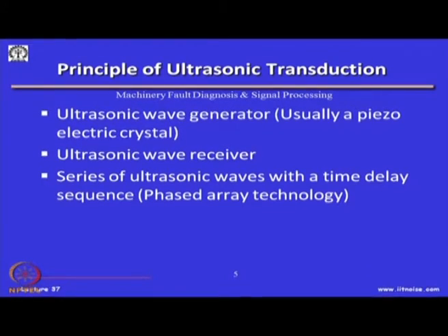So, the principle of ultrasonic transduction, which I just mentioned, is that we usually have a piezoelectric crystal which is made to resonate at its natural frequency. This ultrasonic wave is generated, and the shape of the transducer determines whether the signal is longitudinal, in a shear mode, or a surface wave.